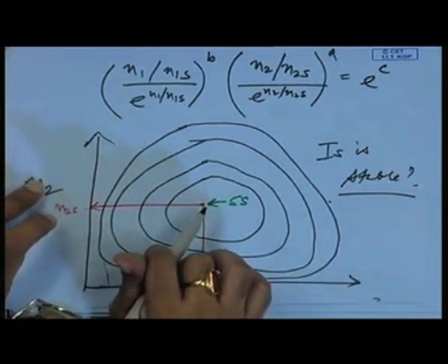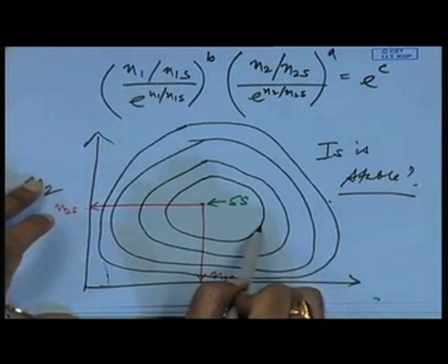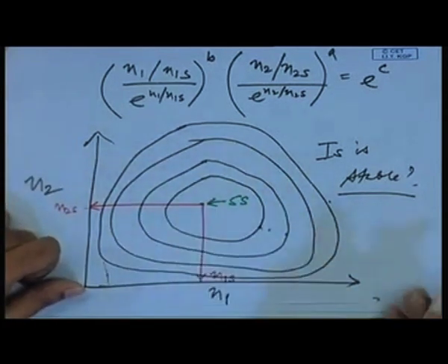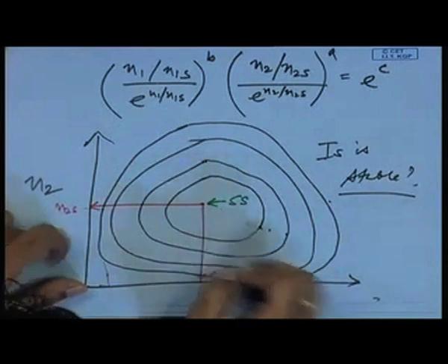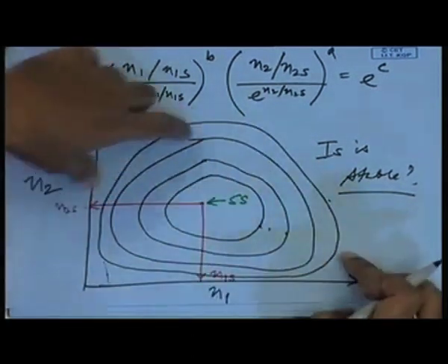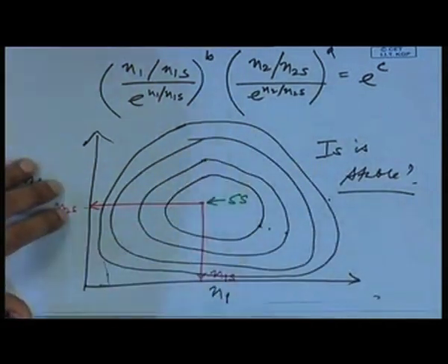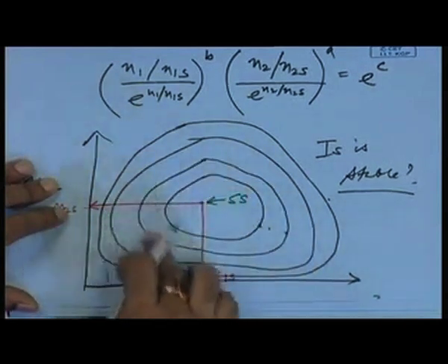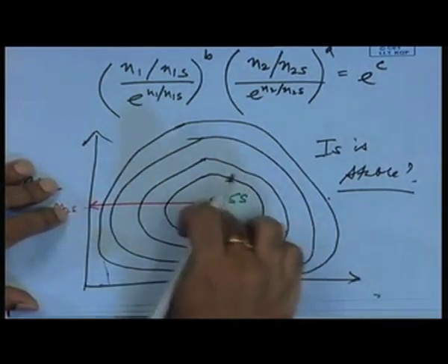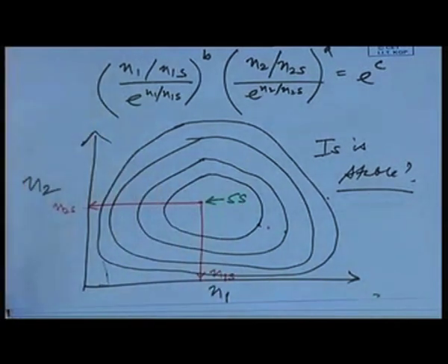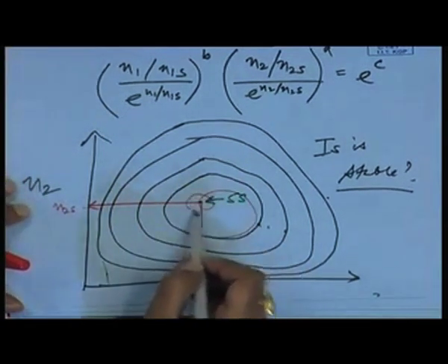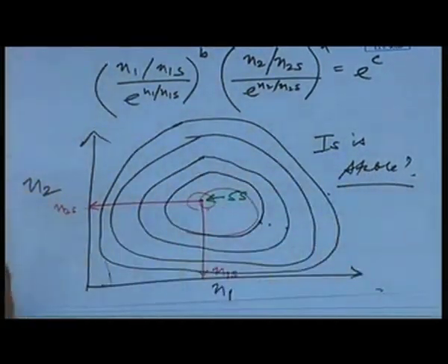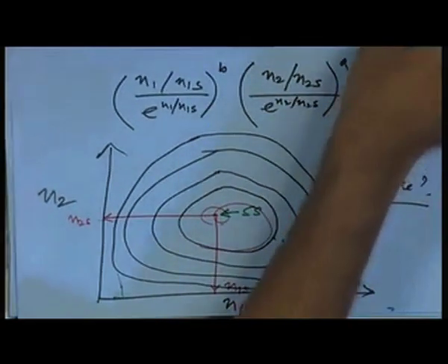Remember, these are dynamic equations we are solving. So, for one set of initial conditions we will be on this trajectory, for another set we could be somewhere here, and if you keep changing the initial condition, you could go further away from the steady state. But for a given initial condition, the system will continue going on this cycle forever. It is not going to come in like this. That is not going to happen. It is going to go on and on in these cycles, the reason being that the real part is 0, the system being neutrally stable.